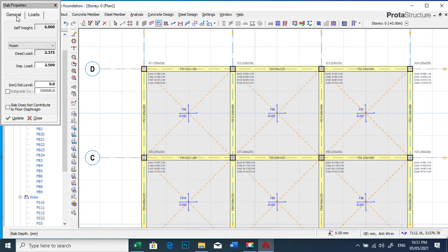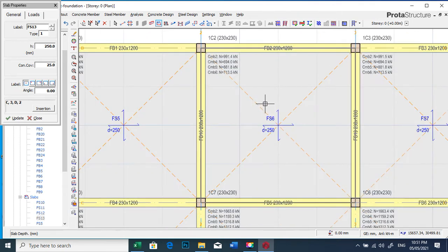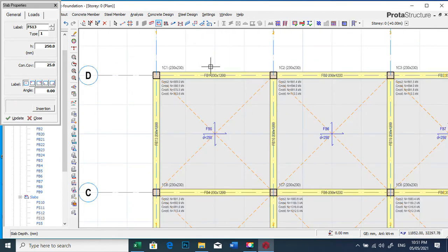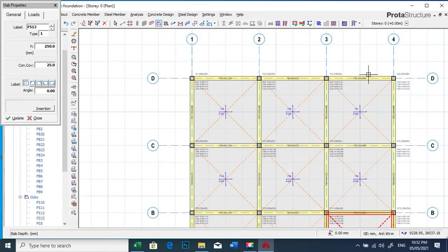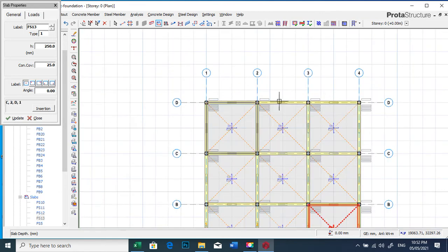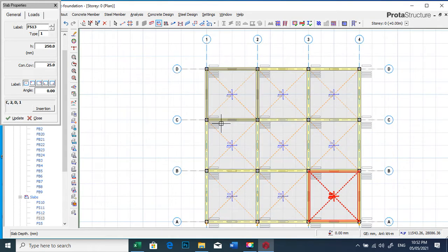Okay, everything is okay. So we've done that, and we can either input wall load there, or put wall load on, depending on where the wall loads are. But you need to check your architectural drawing to see where the wall loads are for you to input.